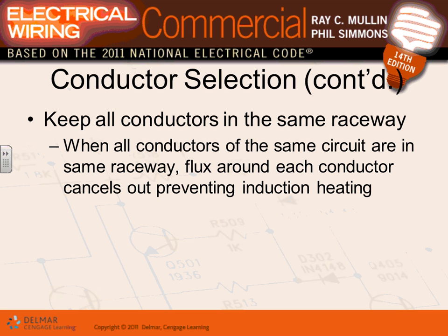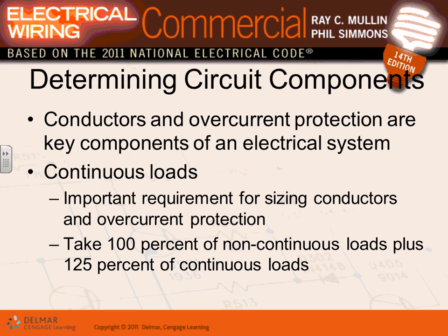Another thing when it comes to branch circuits, guys, very, very important, is inductive heat. What do you do for phase A, phase B, phase C, and a neutral in a multi-wire branch circuit? Do you put them in the same cable or conduit? I hope so, yeah. What happens if you put branch circuit phase A in one conduit, phase B in another conduit? You get inductive heat. So almost always, we're going to group all the conductors of the feeder or branch circuit in the same conduit. So keep this in mind.